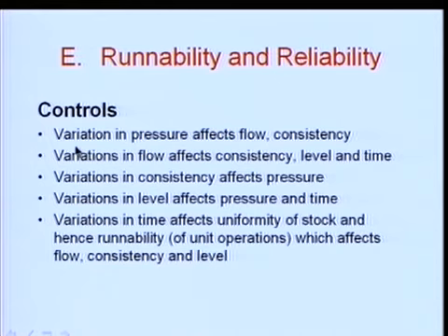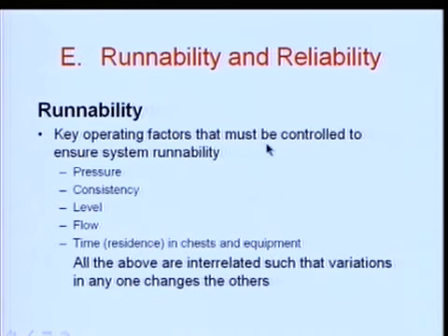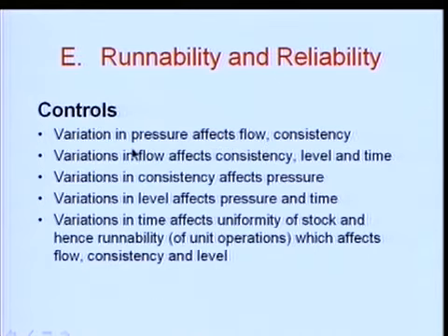Controls, basically that's what we said here, the key operating factor that must be controlled, and hence what are we controlling? We're controlling pressure, temperature, consistency, flow. Variations in pressure will affect flow, which affects consistency. Variations in flow will affect consistency, of course. It will affect level in different chests, and of course will have effect on time. Variations in consistency affect pressure. Variations in level will affect pressure and time depending on the chest.